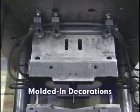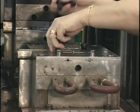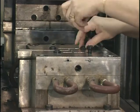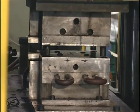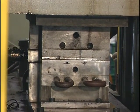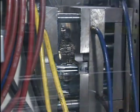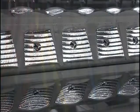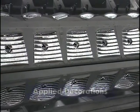Molded-in decorations are those machined into the mold, such as textures, or by implant, as with two-shot molding, where an insert is placed into a mold and then molten plastic is injected around the exposed areas of the insert, creating the part. Even pre-colored plastic resins are considered molded-in color. Applied decorations are added to the plastic part after molding.